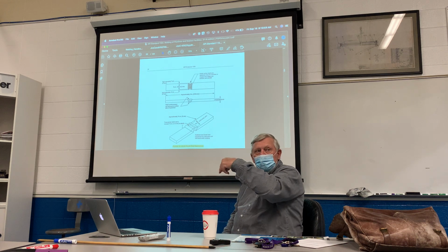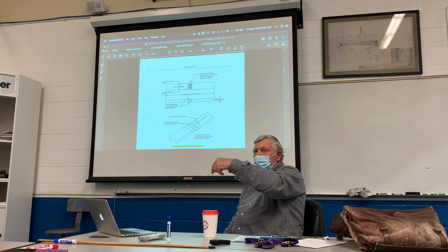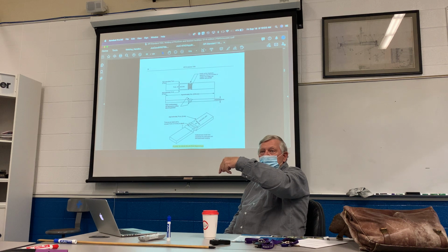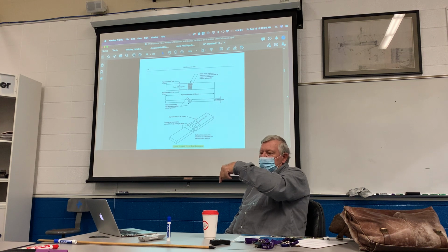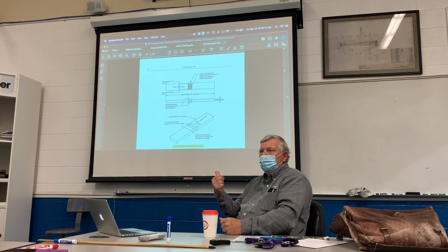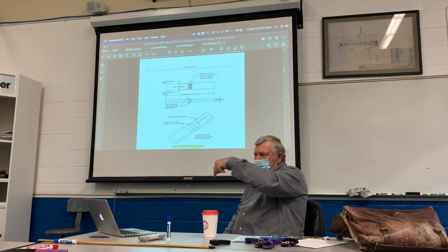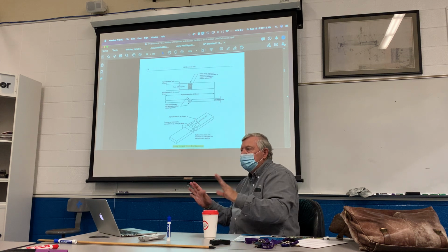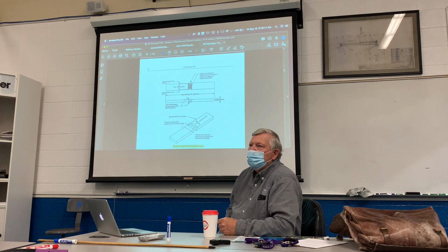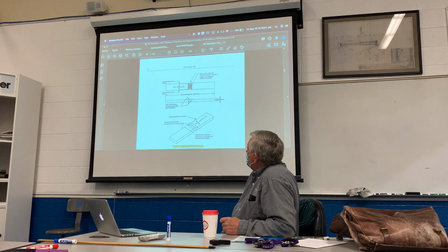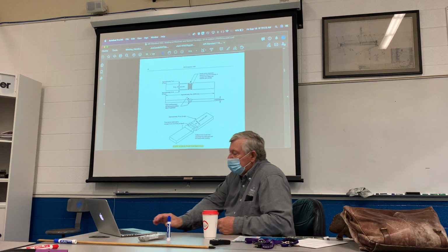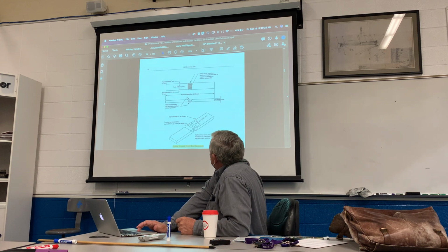Because if you ever cut something and there's a piece of slag or something in that material, you'll see it, right? You see a little black dot. So I cut across there, and if I see anything in there, it's a bust. If I can wash all the way across and go all the way through that weld and not see anything, then I pass it. That's one way I get around it. Anyway, that's what a nick break looks like.